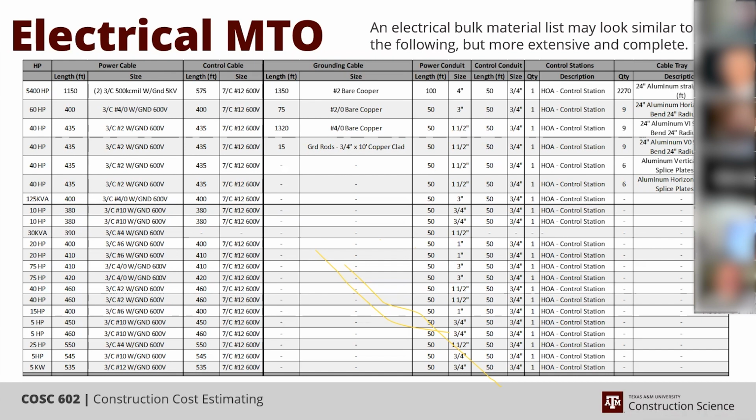So the wires running between the two buildings are going to be on one set of cables, and then your other cables will be running from the MCC to the motors. The exception with what I just said is that you do have cable tray that drops down to 6 inches wide.